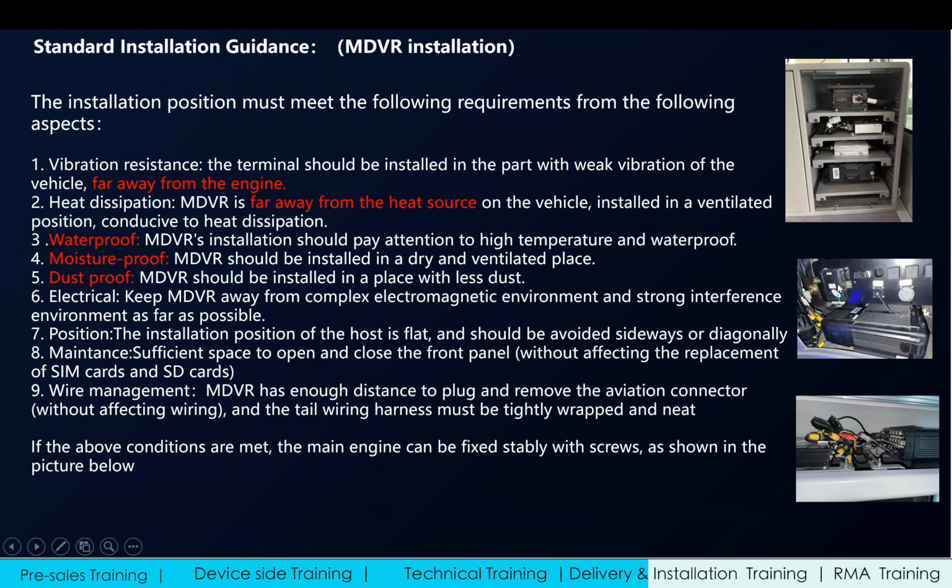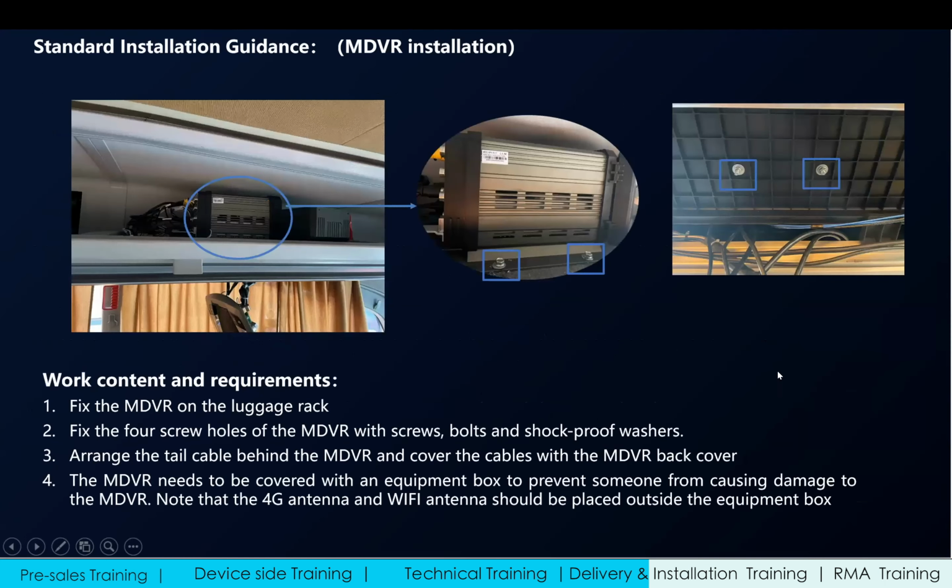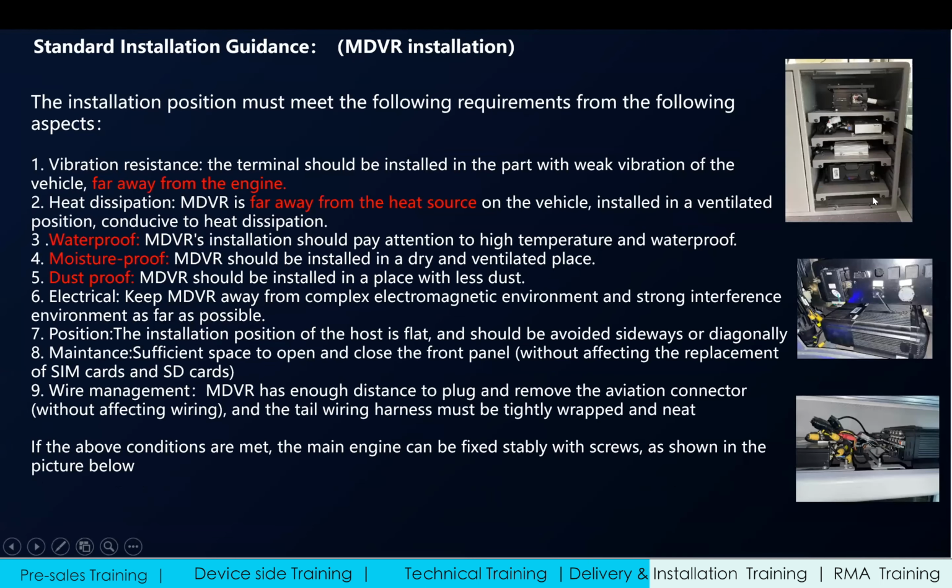That cannot be accepted, because after several days of the vehicle shaking all the time, the hard disk will be damaged. Good installation should have all the screws fixed, and the MDVR should face the vehicle directly, with the mainstream of the vehicle.